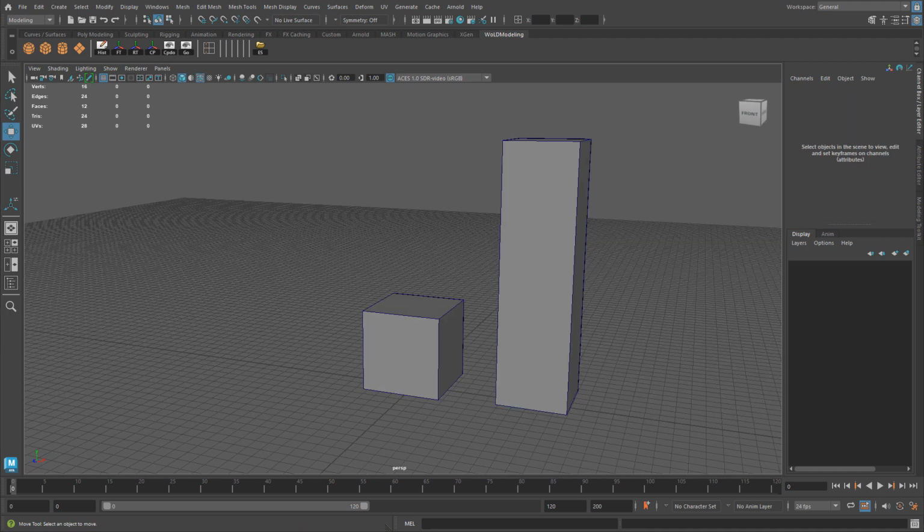Number 18 is resetting Maya preferences back to default, back to the factory install. So sometimes you mess up Maya so much or something stops working, and you may need to completely reset settings for Maya so you don't have to reinstall. You can actually clear your preferences and then reset Maya to what it was like when you first installed it, and that fixes a lot of problems.